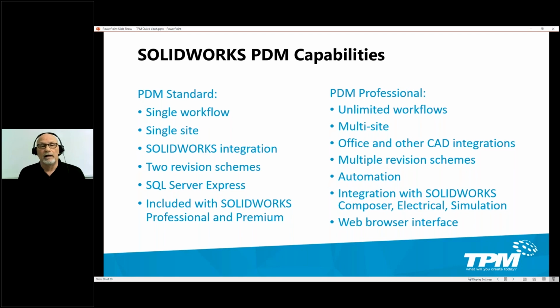And it also has a capability of having a web browser interface. We've shown it with the File Explorer integration as well as SOLIDWORKS integration. But with PDM Professional, you can actually have a browser-based system. So someone can launch a browser and point to a web server that's been configured for SOLIDWORKS PDM and access it that way, instead of even having to install the PDM client, which then integrates with the File Explorer.